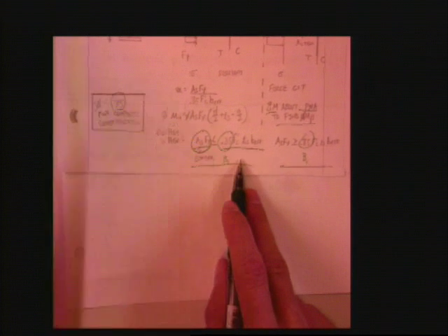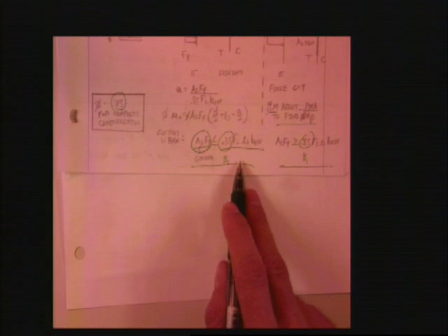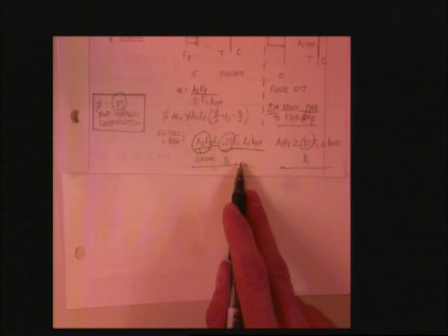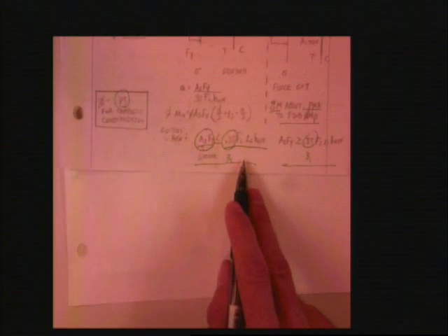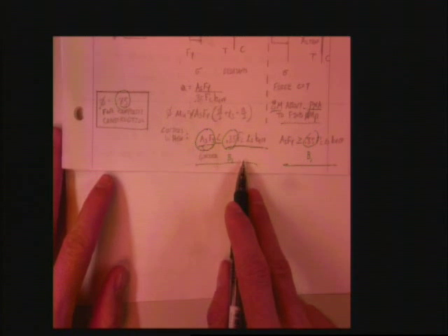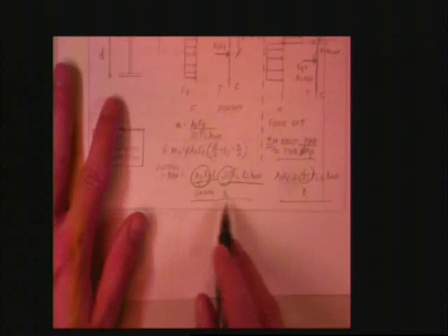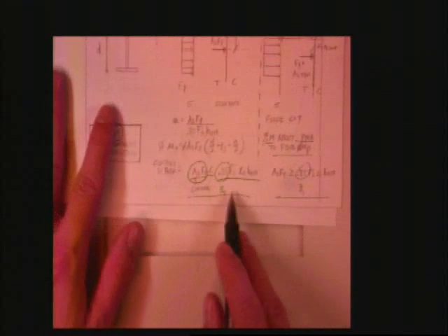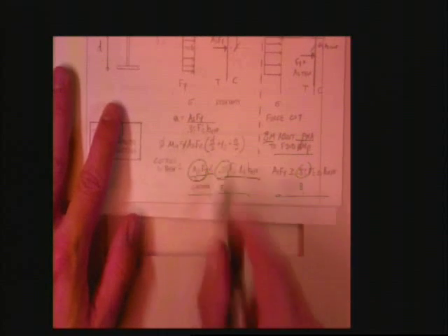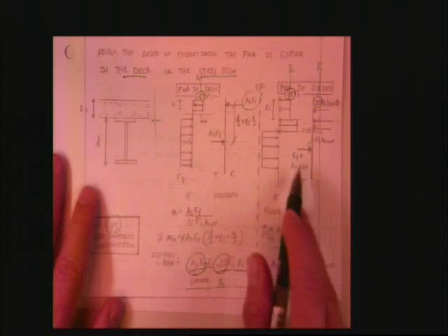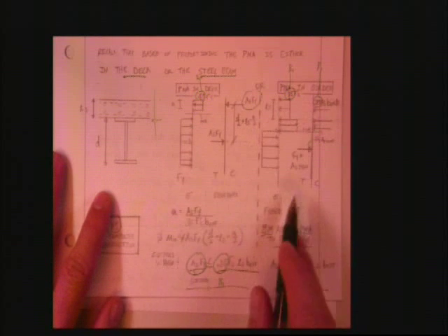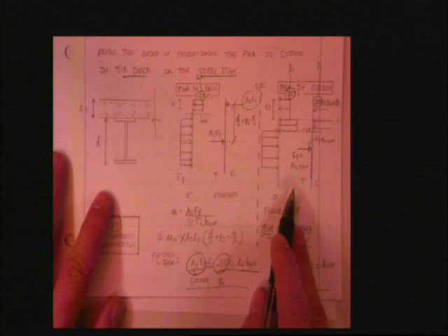This is for a very idealized case. You could easily add some craziness to it, and then you're going to have to go back to what's happening. You can't just use the equation every time. Sometimes you have to understand, actually all the time in this class you have to understand what the equation means and how it works. Okay, so say our life is easy and beautiful and this works out. If the plastic neutral axis is in the deck, we use this circumstance, and if the plastic neutral axis is in the girder, we use this circumstance. Okay?